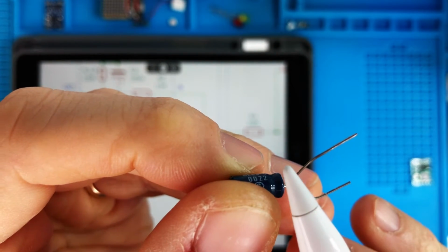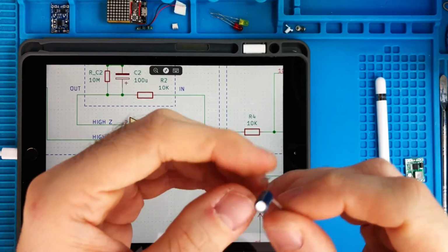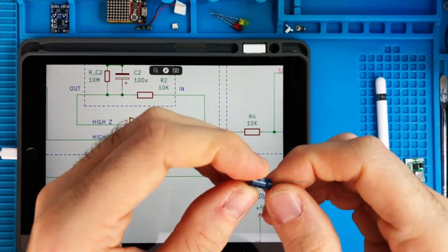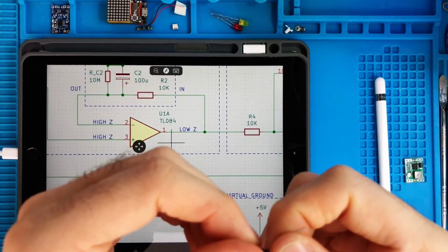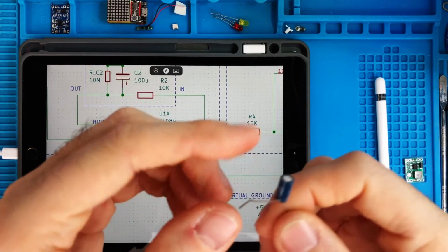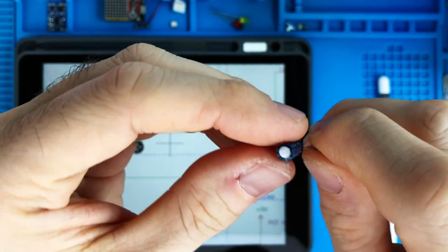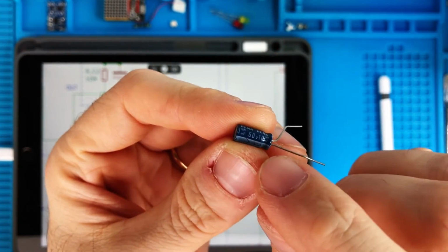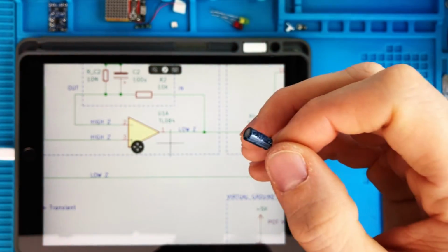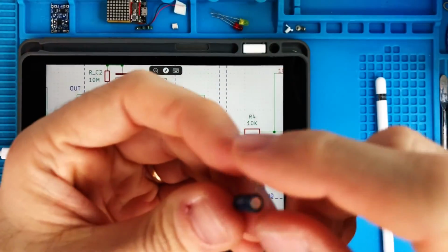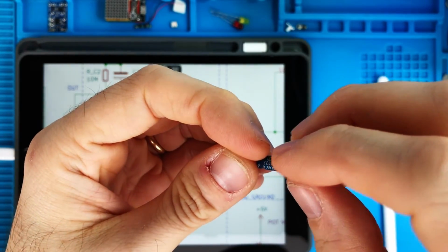So what is the polarity of a capacitor? Big capacitors are constructed by creating a layer of oxide by electrochemical processes that occur in the factory, while they put a voltage which is bigger than the maximum voltage written here on the capacitors, and they create a layer of oxide which completely surrounds a metal, which is a sort of stripe in this kind of cylindrical capacitor, wrapped in a spiral way in order to fit it in this small space.